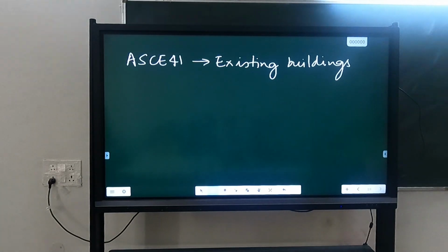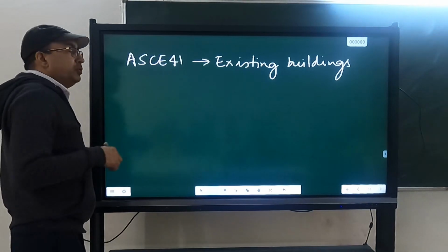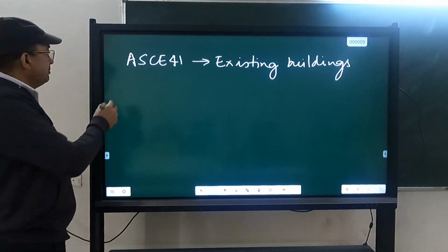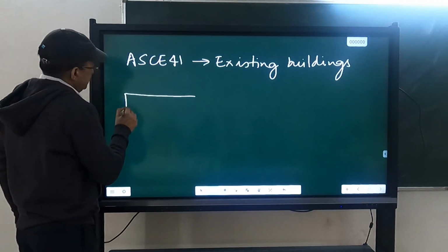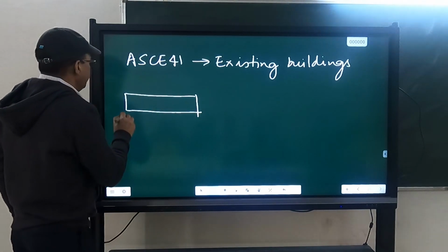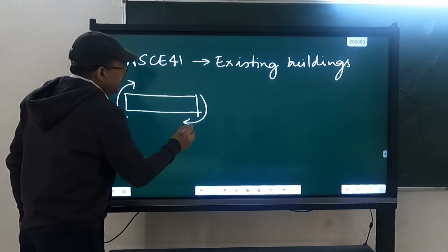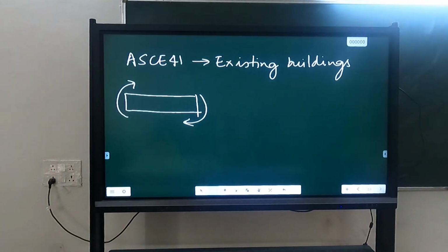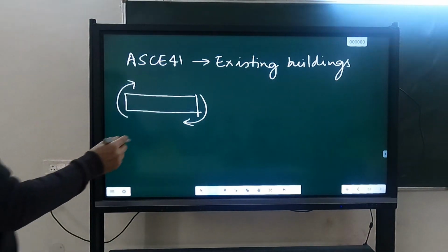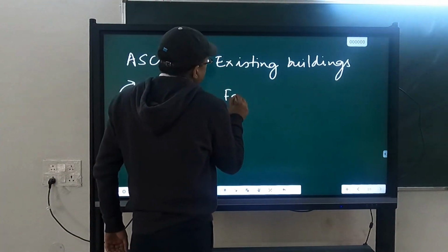Similarly, the capacity shear design may or may not be done. In a member, if capacity shear design is performed, it is designed for capacity shear, meaning its failure in shear is protected.